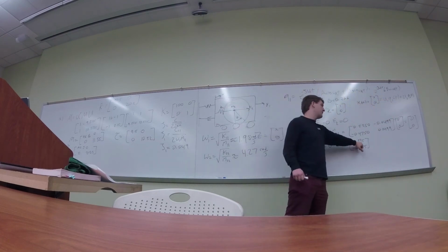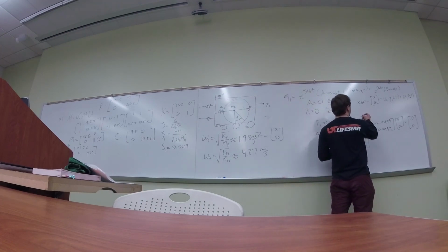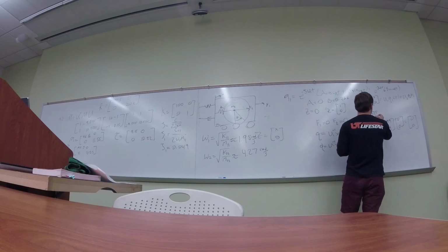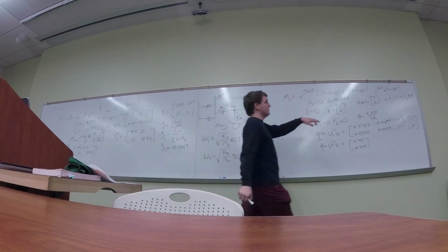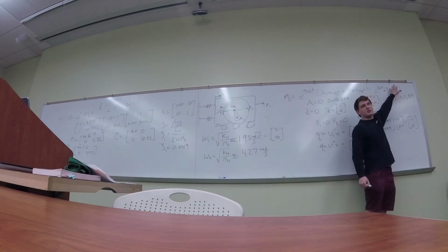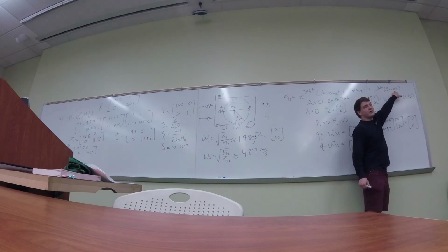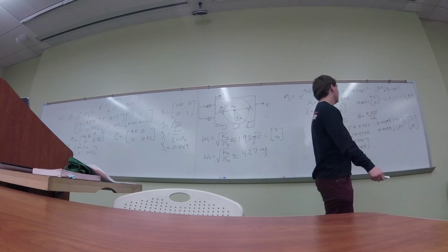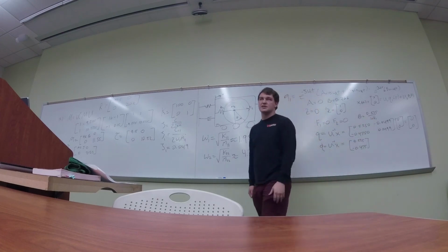Q1 dot is equal to 0.525. You're going to find out that B will be equal to 0.525 divided by omega d1. Because this sine will become a cosine when we take the derivative. Cosine of 0 is 1, so you get B. This is going to still be the 1. But when you take the derivative, this omega d1 comes out. So it's going to be B times omega d1 equals your response at 0.525, so B is 0.525 divided by omega d1. Now you have B.